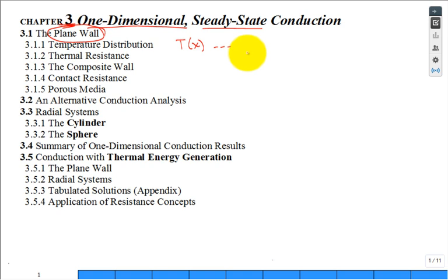It's a line, a constant slope through the wall. And we are able to come up with a thermal resistance, L over kA. So L is the thickness of the slab, A is the area through which the heat is flowing, k the thermal conductivity. Then we were able to put together slabs in series, like a composite wall, as well as putting these resistors in parallel, so making a thermal network just for conduction. Then we had contact resistance, R double prime thermal contact, funny units.